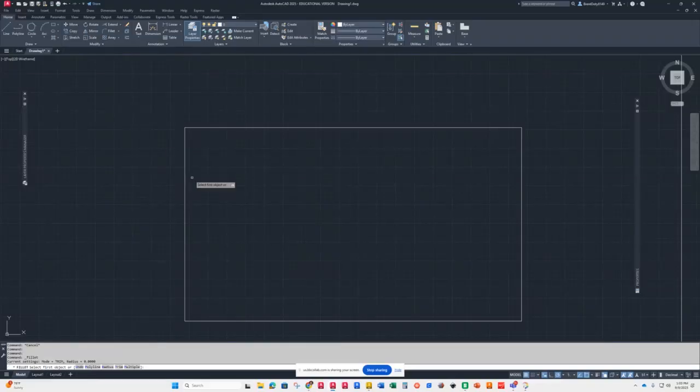And so if I go into fillet and I just start trying to pick things, what's going to happen? It's going to trim or do nothing. In this case, it's not going to do anything because I didn't set the radius. So I guarantee if you have a problem and you go, why won't this thing round off these corners? Well, it's because you didn't set the radius.